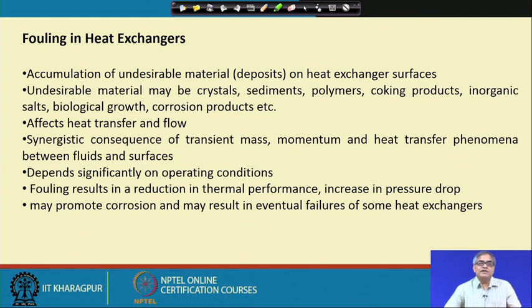It affects the heat transfer and the flow. So, basically two things will happen. The heat transfer passage area will change, and the heat transfer surface condition, that means the roughness of the surface, will also change. So, obviously, both of them affect heat transfer and fluid flow.